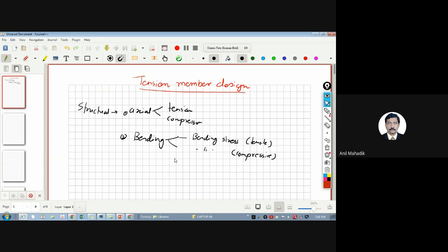So mainly these are the forces actually in any steel structures. Generally in steel structures, we don't allow any torsion, so I'm not taking that torsion into consideration. So tension, compression or bending stresses, that's it. Axial forces generally come in columns. I think all of you know this. We get these forces in columns or suspension cables. In columns, we get compression. In suspension cables, we get tension. And bending stresses we get in beams, and also in columns. Don't forget that. Column also is subjected to bending.